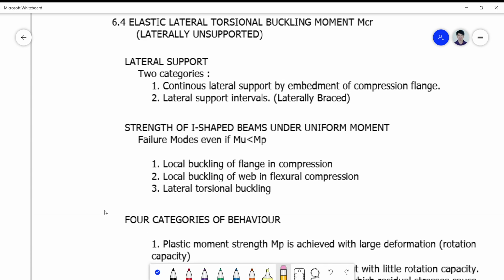So these first two criteria on the failure modes are quite similar, based on the concept of plate stability analysis for compression. While the last is the failure brought about by the effect of lateral torsional buckling due to the insufficient support condition applied laterally to the beam frame.